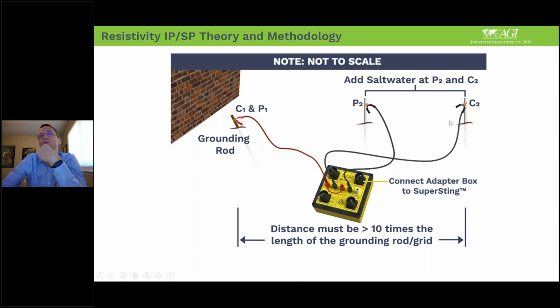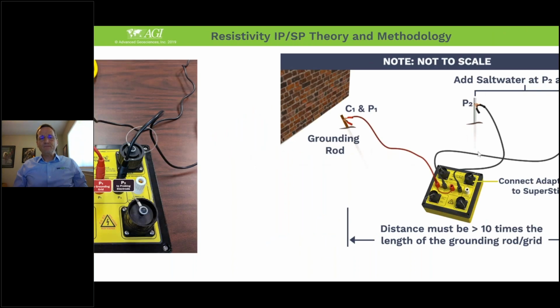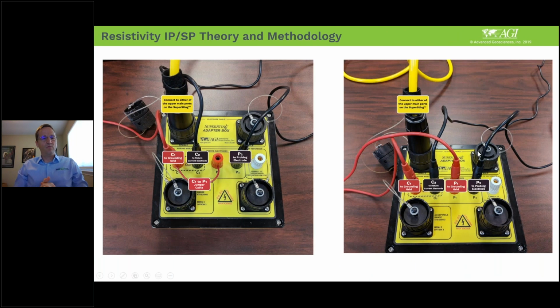And there's some geometry that would be given to you for a project like this. It's to measure the grounding of a system already installed. And you would request that power be disconnected from it so that there's no leakage to the ground. You know, in some old grounding grids, there's some leakage to it. So this is side by side with the jumper between C1 and P1, or the wires going out. And these are equivalent to each other.